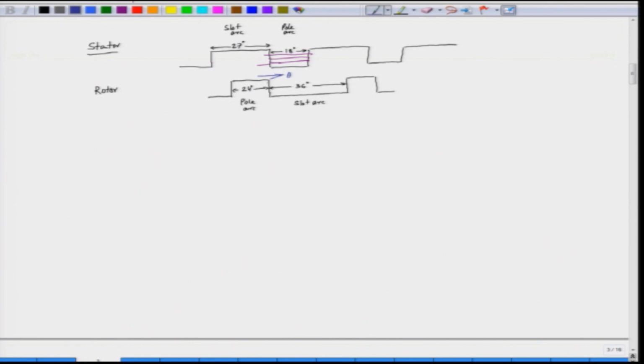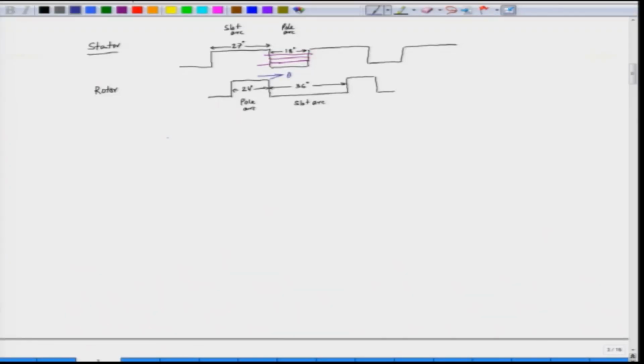So, when the rotor comes under the stator, there is a gradual increase of inductance. The inductance increases gradually, linearly in fact, with theta. So, we can define the inductance as follows: the permeance in this case is mu naught L axial into r theta by L g. L g is the air gap. So, this is the rotor pattern. This is basically a part of a cylinder.